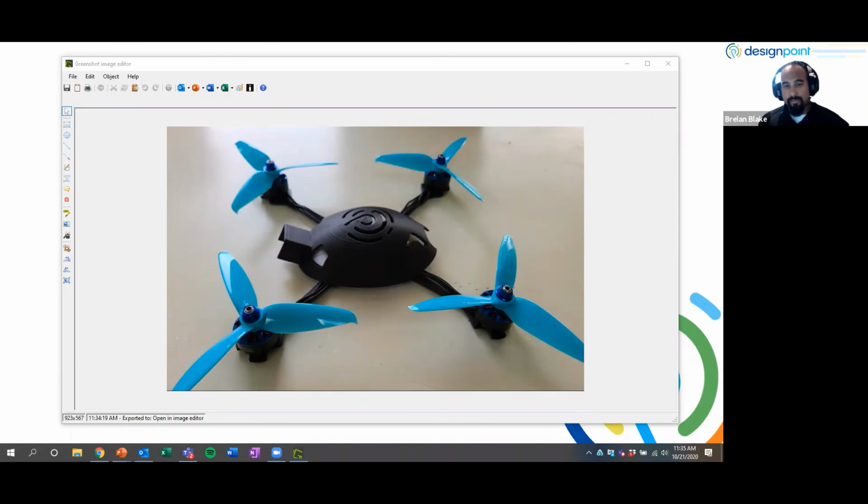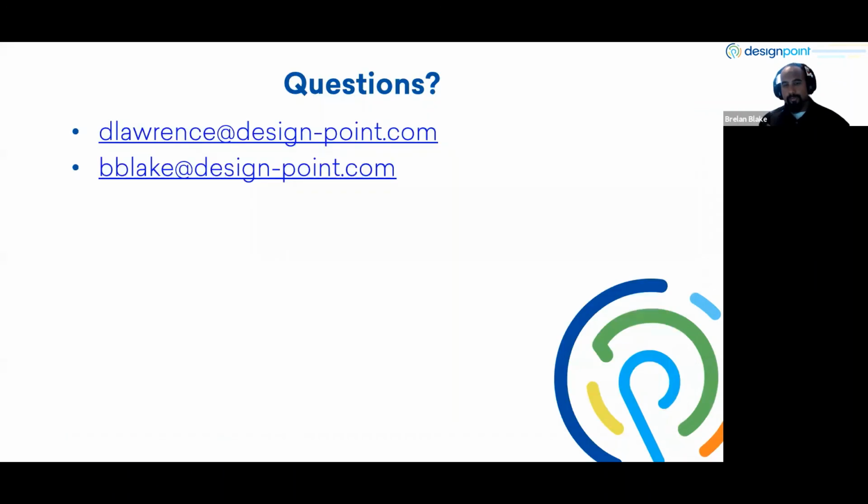Yes, we definitely will change the prints depending on what type of material we're using. As we were showing before, we use continuous carbon fiber with the frame. With that continuous carbon fiber, we want to place the quadcopter frame flat on its back to make sure that we have continuous fiber going the whole way around in the correct orientation. We could turn it on the other axis, but we would use a lot more material just to support the frame if it was turned 90 degrees in the XY.